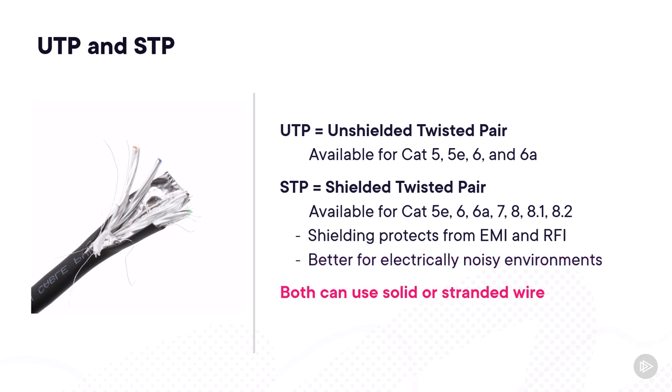Both UTP and STP can use either solid wires or stranded wires. Solid is more common, but stranded might be better if the cable has to make some sharp twists and turns, or if it just needs to be more flexible.